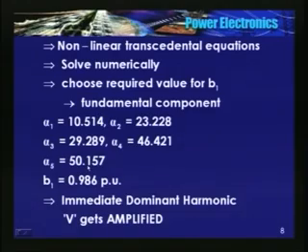You approximate these angles and substitute in those equations, you will find that there is a significant increase in the harmonics. Only when you switch at these angles can you make the 5th, 7th, 11th, 13th 0. If I approximate it, there is going to be a significant rise in the harmonics which are already eliminated. In fact, they will not get eliminated.